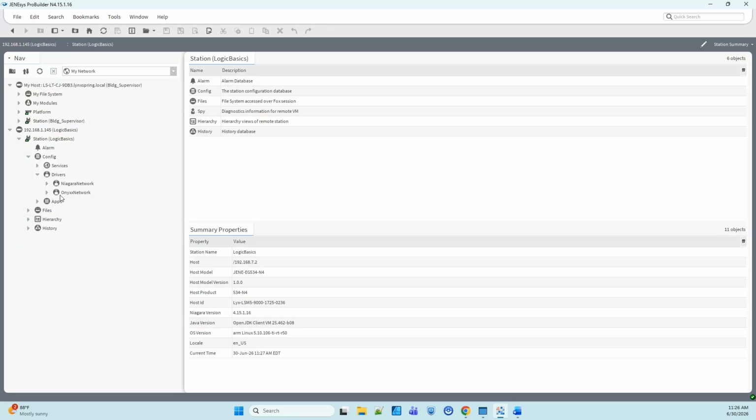It's our proprietary network that talks to not only our onboard IO, that's what I have this Logic IO name here for, but the XM, the extender modules that Bob was talking about, which, fun fact, for the 500 series and 600 series, you can put 8 of them on there. So you can have a total of 306 IO, or 286 IO if you were using like the 514. So we can get fairly massive systems here as well.